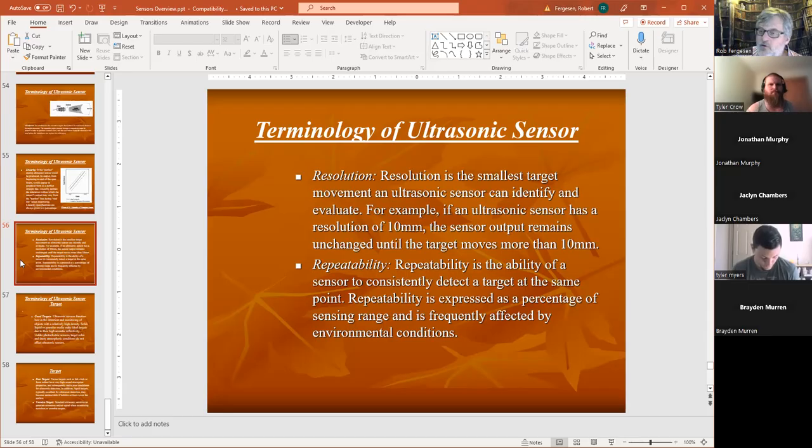As you drain material out of the bottom of your physical tank, it creates a big funnel-shaped cavity at the top. That's hard to measure accurately. Where do you measure on that funnel? Right in the top, right in the middle, right on the side? It's tricky. So you can have a lot of environmental conditions that make a sensor difficult.